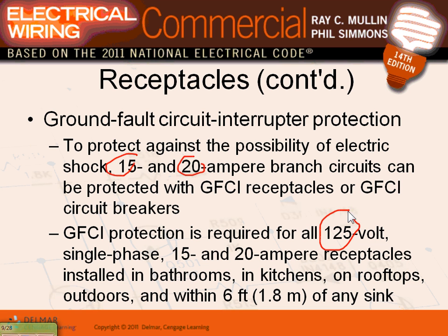Any question, guys? Here are a few places: bathroom, kitchen, rooftop units, outdoors, within 6 feet of any sink. Take our project now. In our project, all the outdoor receptacles are GFCI. Do we have a kitchen? We don't. Well, we have a lunch room.